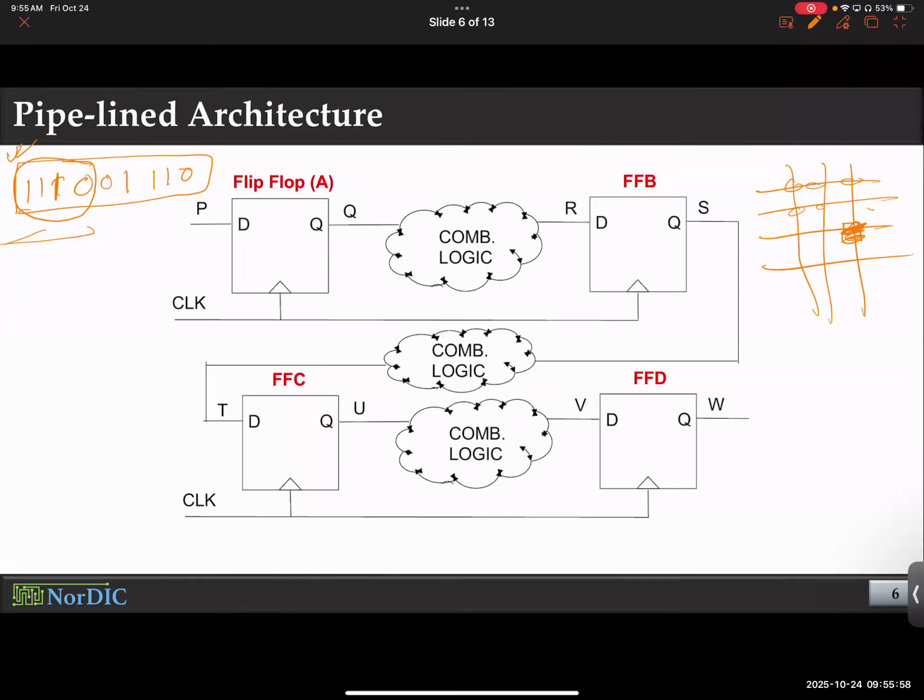Okay, but for this example, I cannot write 16 bits and show you. So 4 bits for row. So I select the row, and then maybe the next 4 bits, 1, 2, 3, 4, to select the column. And then, okay, now I have the row and the column, so I know which memory location you're talking about.